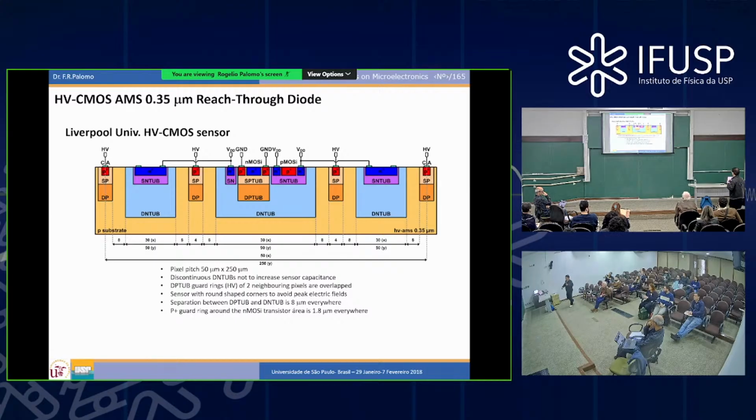Take into account that here you work at 1.8 volts, and from here to there you work in the 100 volts. So it was important to know if the device, once manufactured, was not self-destroying because of the bias. That was the reason for those simulations. In particular, that was my work.